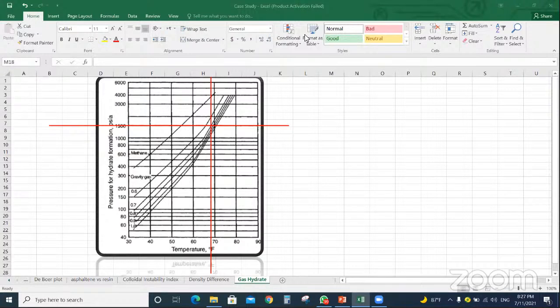The main objective of the SARA analysis is the characterization of asphaltene problems. It will group the composition of the reservoir fluid into 4 groups, like we mentioned in the slides: asphaltenes, aromatics, resins, and saturates. But we have a simple method for knowing the amount of asphaltene in the reservoir fluid by adding light saturate hexane. If we add just some saturate hexane to the reservoir fluid, the asphaltene will be separated from the solution and deposited on the bottom of the cup.